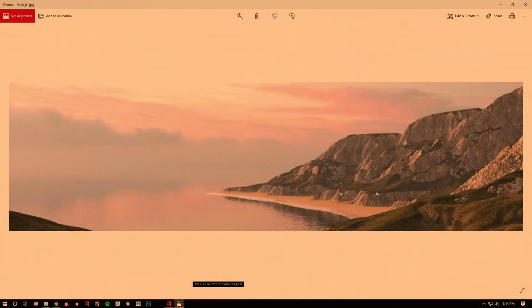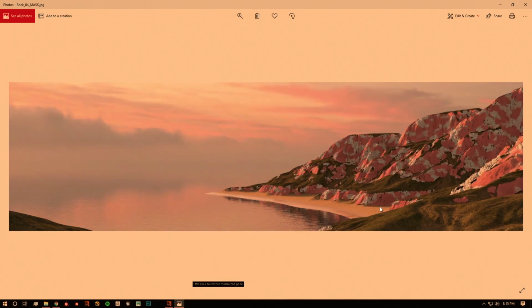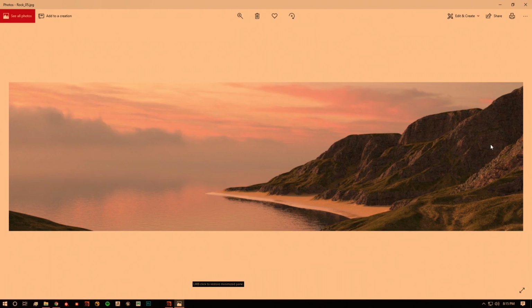So only these interior faces will be extruded as rocks. So at the end of it, I'm getting these really good rock details, and now you can just change any material, put displacement on that, and have different kinds of rocks even popping out of your terrain. So this method allowed me to have these good details on this. You can also have a noise on this material as a mask to have different tile textures basically. So some of the regions will have more tiling, so that it will not look so uniform.